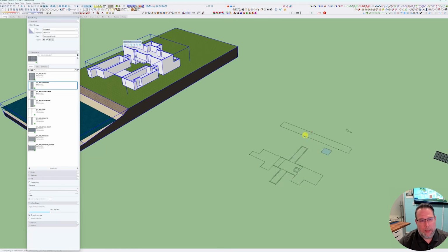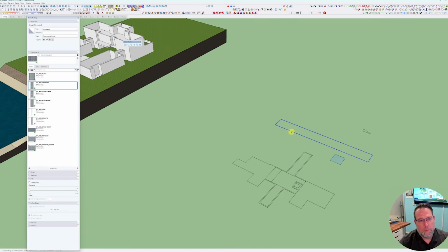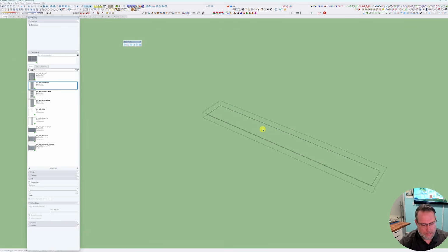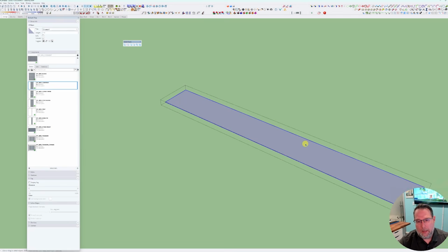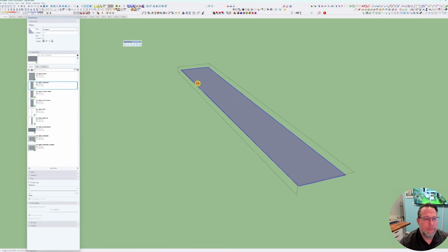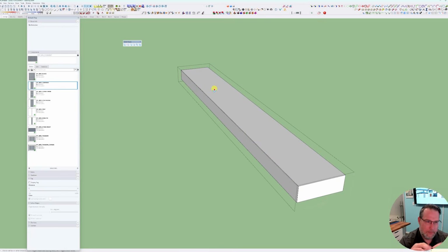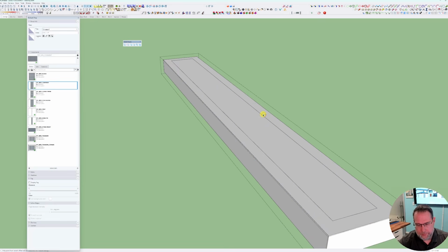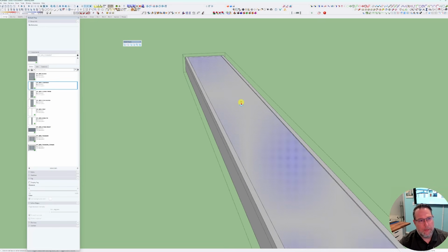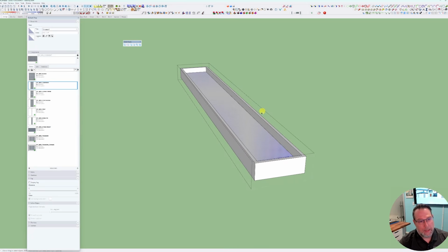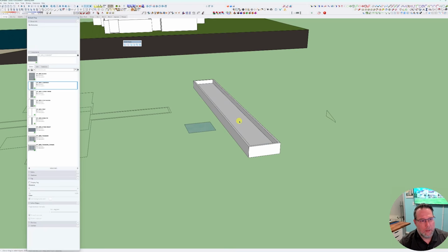And so I even have, this is kind of like a reflecting pool, if you will. So let's build a pool real quick, and I'm going to show you that. So again, I'm going to Control A, tap plus sign to make this a face. I'm going to pull this down. I'm just going 48 inches because this is just going to be a thin reflecting pool. I'm going to offset in 8 inches for my walls, and then maybe push this down even just like 24 inches. And then I'm going to make a copy of this bottom and come back out. So this is my solid pool.